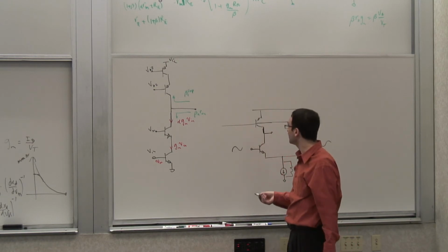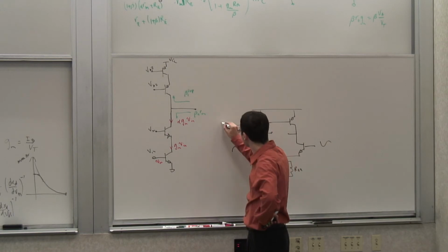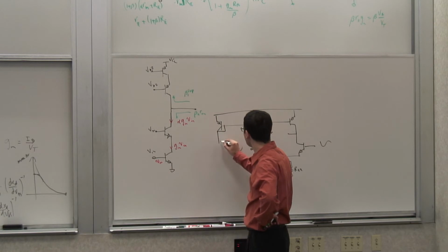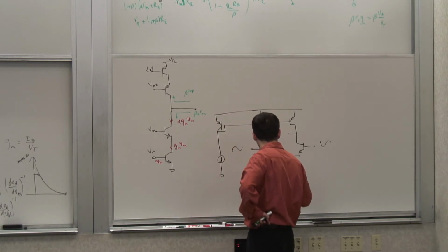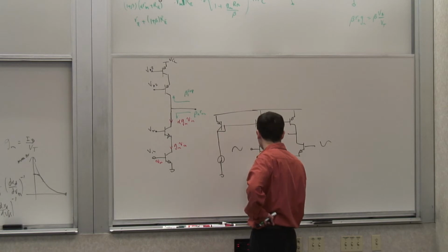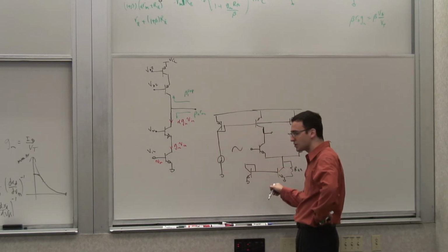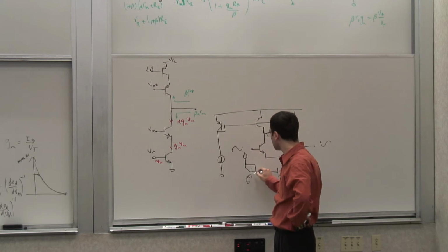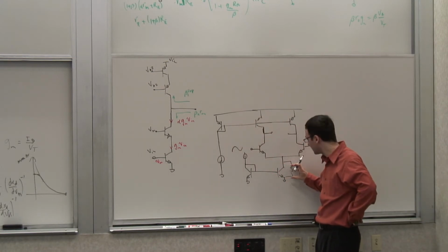Now, one question that was raised at that point is how do you make these current sources? How do you bias these guys? And we saw that you could actually make these reference branches like that. It could be biased by some reference current. And here, this could be a basic transistor that could be biased with another branch using a current mirror. We saw that in a current mirror, these two VBEs were equal. So to first order, these two currents have to be the same. Of course, there was the base current to be accounted for and the early voltage, the early effect.